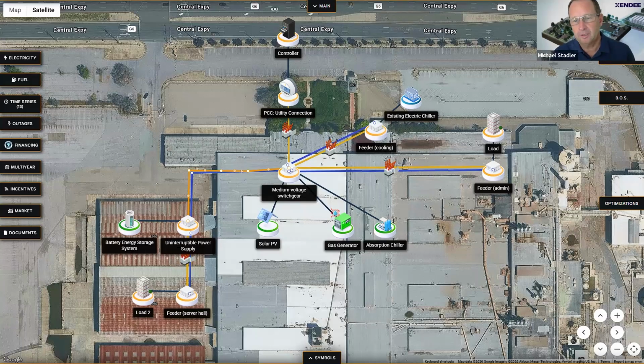Can multi-node be used without grid connection? Absolutely. We just modeled this with a grid connection, but it can be done without a grid connection. The only thing, of course, is that you should keep in mind that we're doing this down to a 15-minute basis. So you need to probably do a couple of iterations in this design mode to have enough capacity if there would be a bottleneck in the system. Here we can always use the grid, but if you don't have a grid connection, then you have to probably also go into the one-line diagram and see if you have enough capacity to serve your loads on a smaller time step. But it's easily possible.